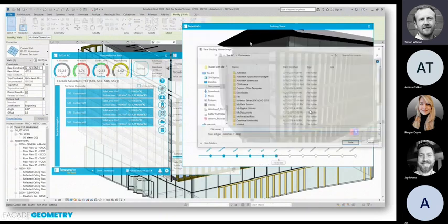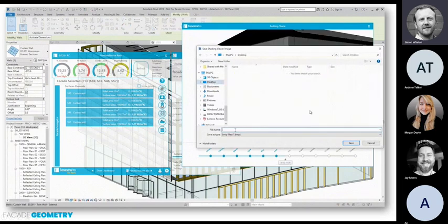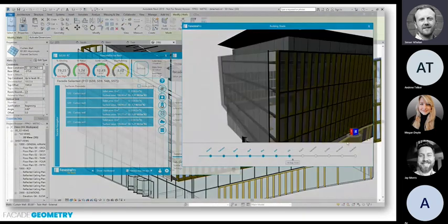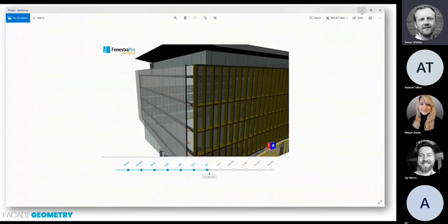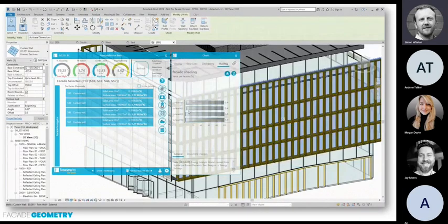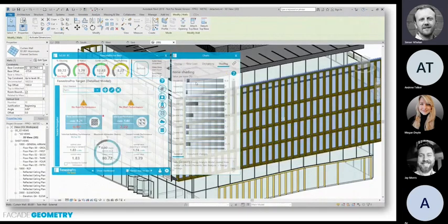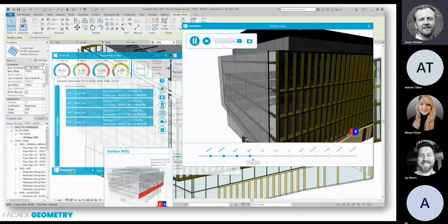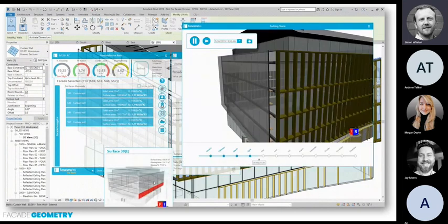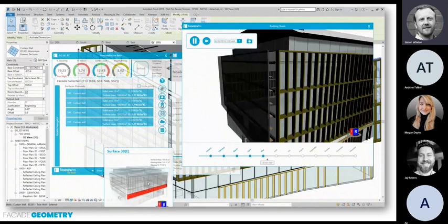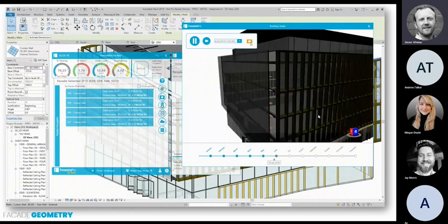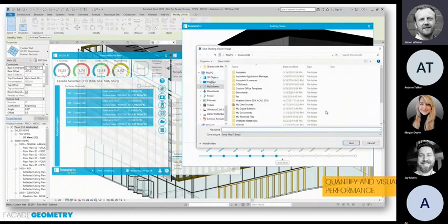Shading will affect your heat gains. So if I've got big shading canopies or I've got a building across the street, I'll have a greater level of shading, but I'll have lower heat gains hitting that facade and penetrating that room. Shading will also affect your daylight and performance. So, again, it's just good to be able to understand and weigh these things up against each other.